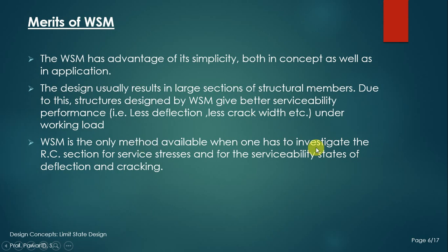WSM is the only method available when one has to investigate the reinforced concrete sections for the service stresses and for the serviceability states, for the deflection and the cracking. So these are the merits of the WSM method.